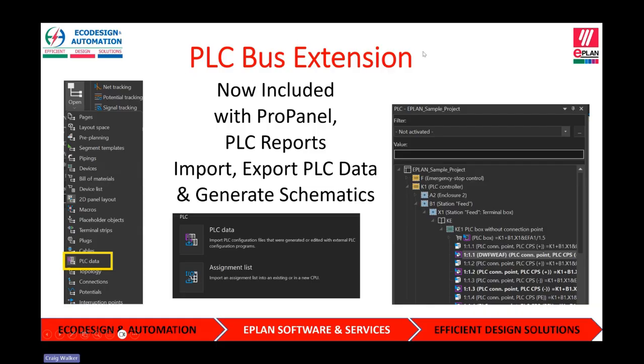This is traditionally in P8, and I know quite a few people are familiar with using it. What it involves is you now have a PLC data navigator, which allows you to navigate your PLC setups. It allows for the generation of PLC reports, like PLC overview, which we find is in high demand. We generate that for nearly every project we do.